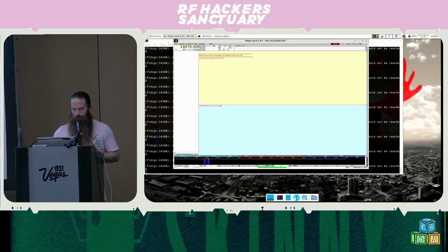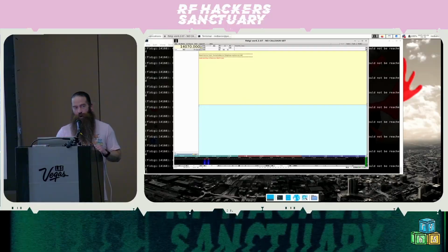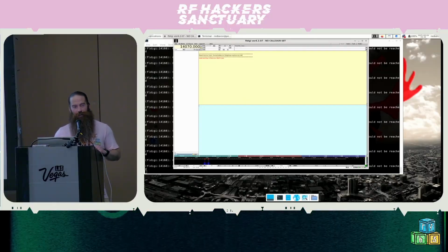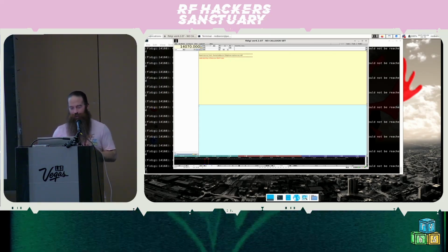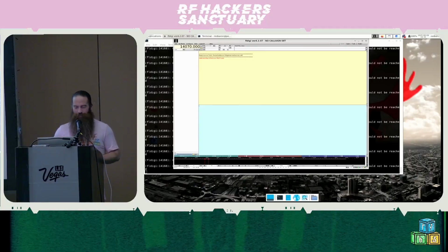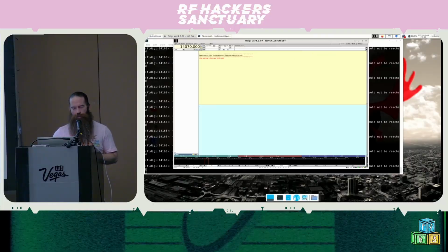Now, if you do that, make sure you double check the sample rate of the audio file and the sample rate that you have set in the flow graph, because that is something that just bit us a few minutes ago. 8,000 hertz, as it turns out, is not the same as 48,000 hertz, but it's easy to miss. But yeah, that's what you need to do for generating new flags for any of the modes that FLDigi supports.